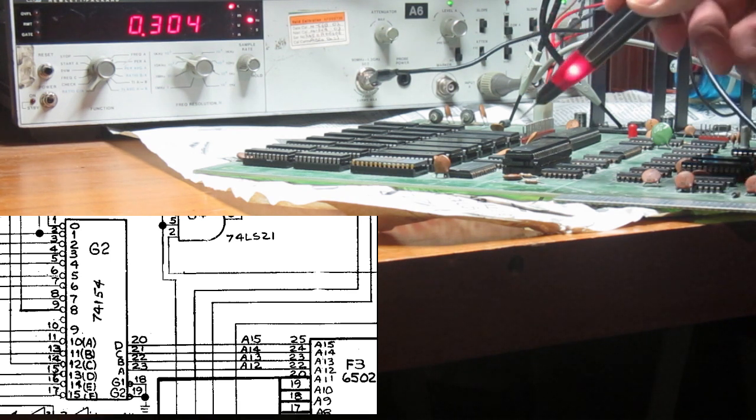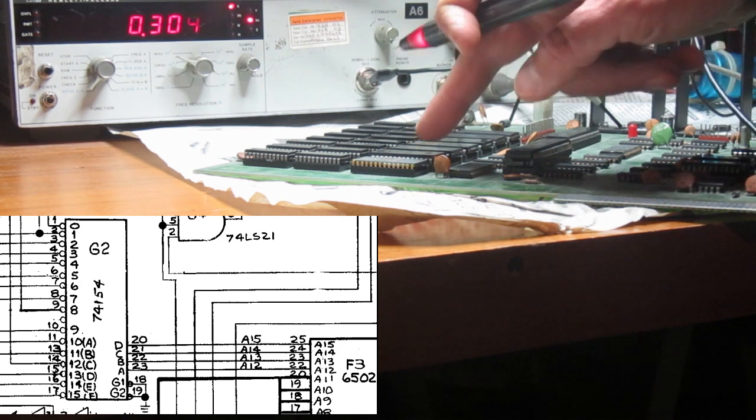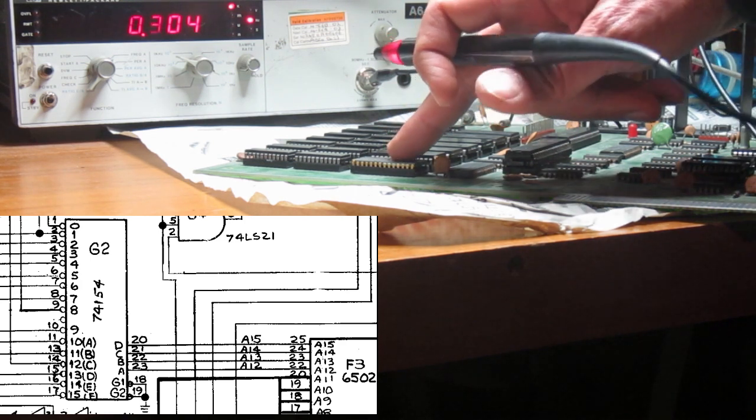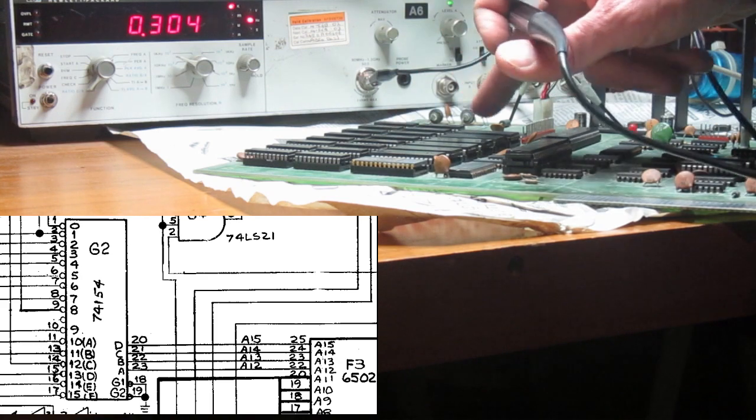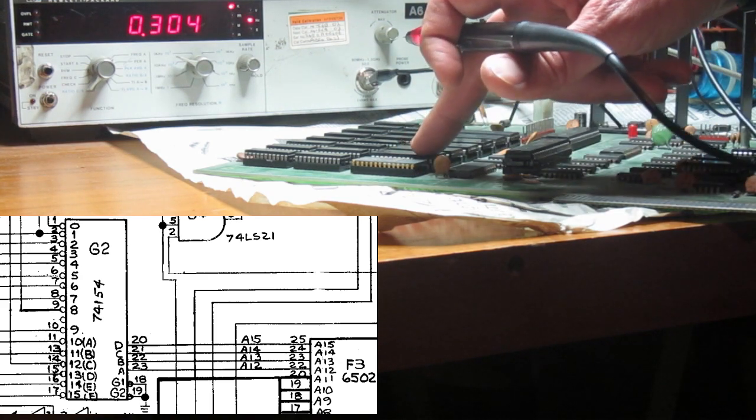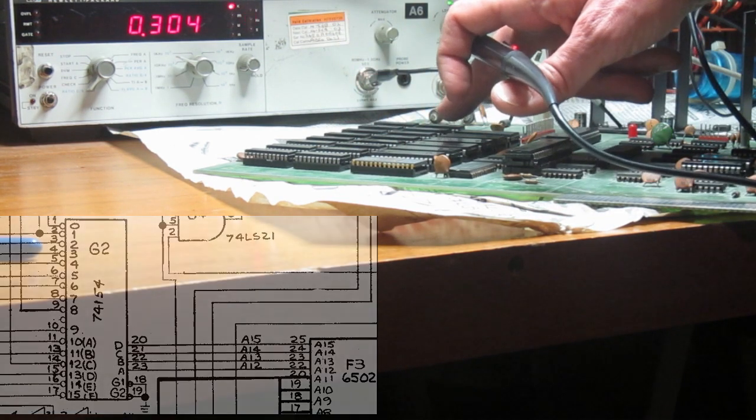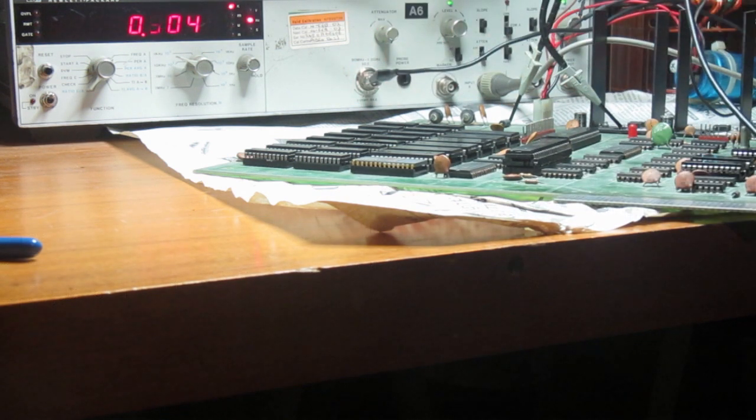So this can help. Of course, on the board you can also check the ROM enables. All ROM enables should be toggling. All the RAM enables should be toggling in this moment. So you can check a whole lot of things with an NOP generator installed. It's a good way to find hidden problems in the logic board.